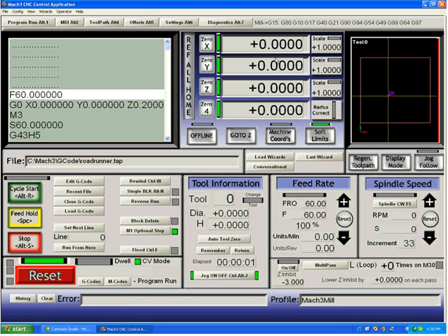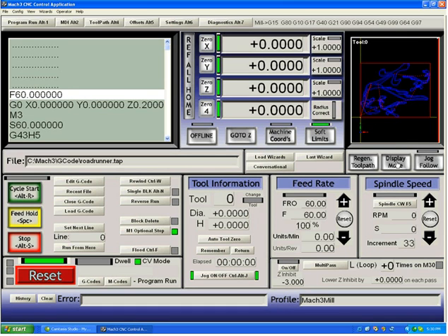Normally, that LED is off because you know you want to be at 0, 0 when you're at the left-hand corner of your material. If I switch my display mode to job control, you can now see my crosshairs are at 0 and I'm ready to cut my piece. Most people will leave their display in this position.